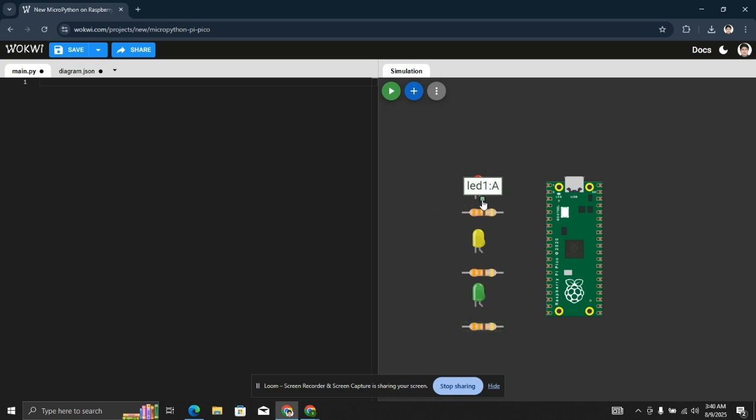Now we have to connect the wires, okay, to the resistor and the resistor into the circuit. For that, please connect the long leg of the LED 1 to the R1 resistor, pin 1. Just connect this one to the R1 resistor. So we have successfully connected this one, okay. Now just connect this one light up to here, the GND.1 of the Pico, GND.1, okay.